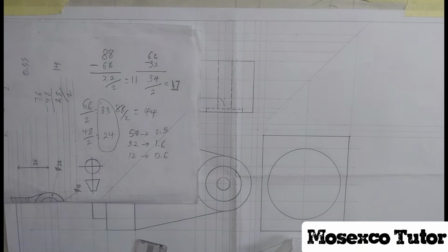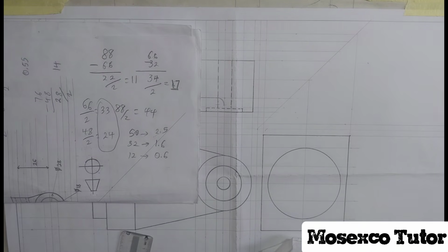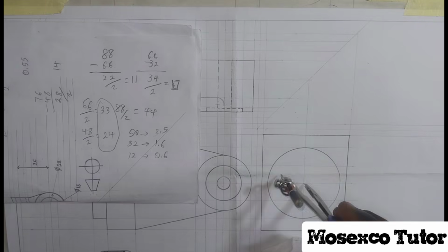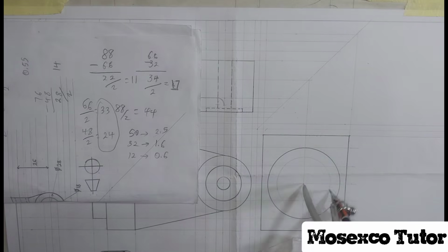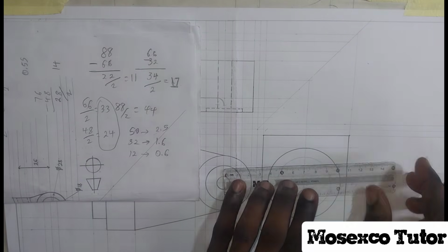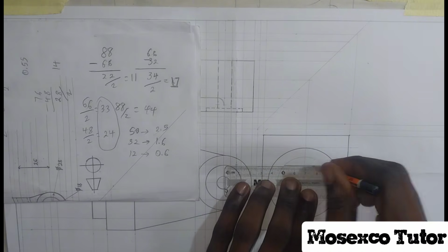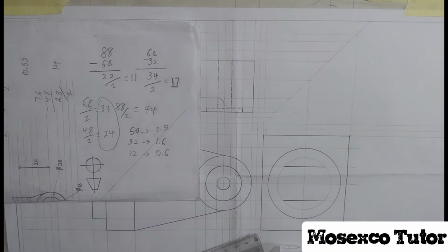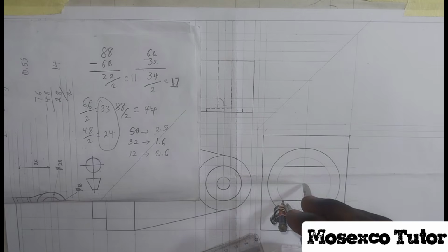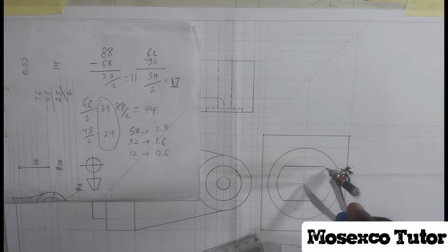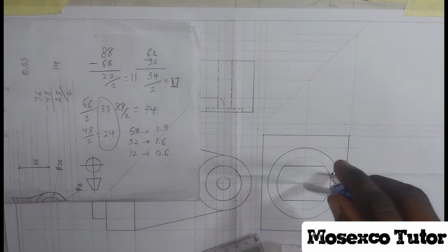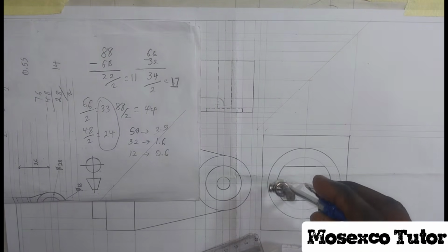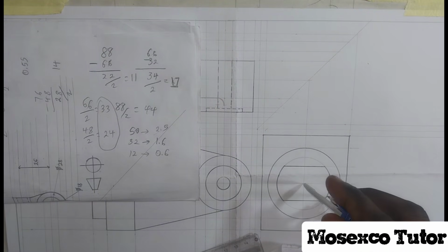Now to get the second circle, I take radius of 2.4, which is half of 4.8, but as a faint one. Now in between here, where this line meets, I join that thick line, not the center, but the other two. Then I take my compass again to thicken the left and the right arc, so that I can have this figure. So having this figure now, I proceed to the other parts.